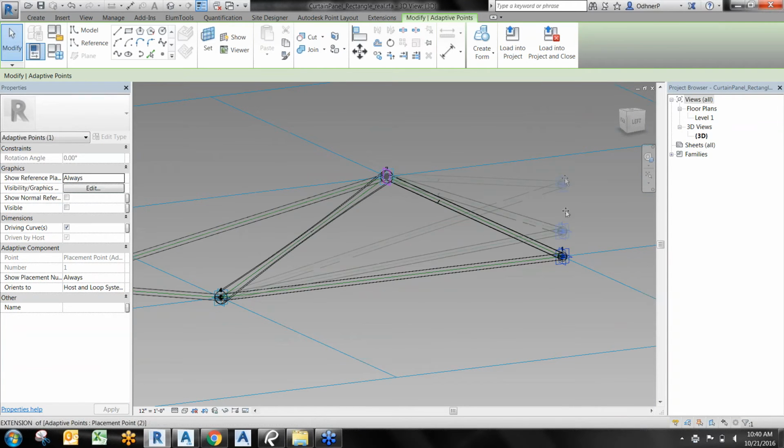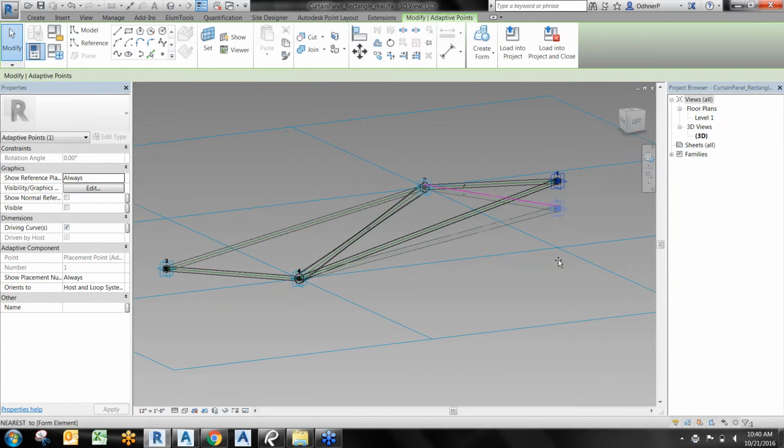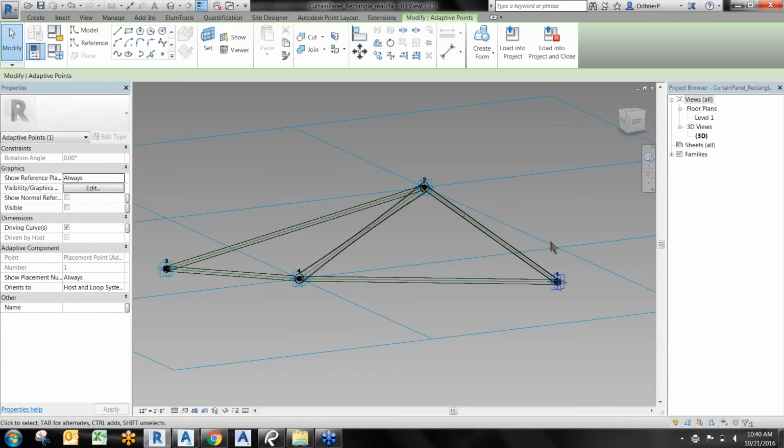It's always good to test these out, as it is with that curtain wall. And we can also test these out. So just remember, the higher, more acute the angle here, Revit and even the geometry just are not going to be able to calculate. So keep these angles pretty modest if you can, actually.